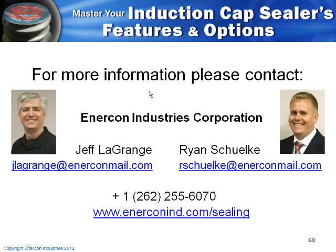All right, we've got time for one or two more questions. The next question is, what is the recommended clearance between the cap and the product? That's a good question. Typically, the important piece is that it's consistent. We've got some applications that we run as low as 1/8 of an inch or 3 millimeters. There are other applications that we run higher than that, in the range of 10 millimeters from that side. It really depends on the application.